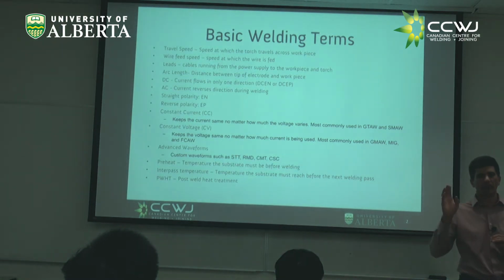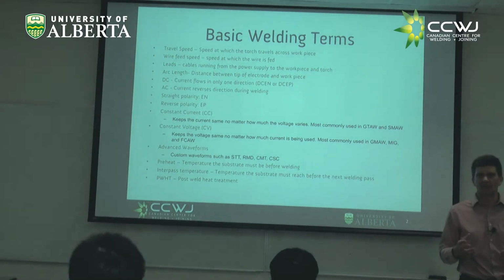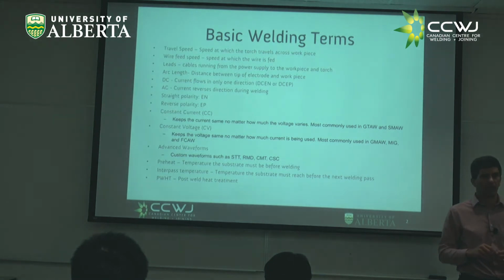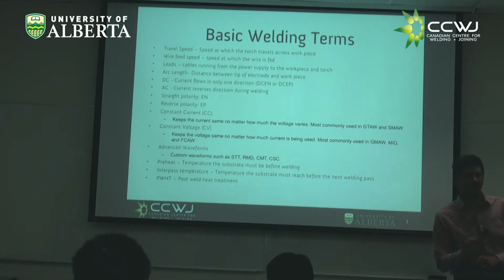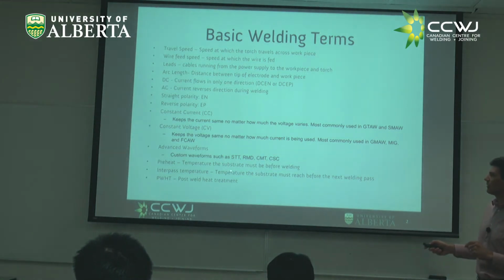If you have a weld that is too hard, then you can increase the preheat, and the weld is going to be softer. And this has nothing to do with the heat of the preheat softening the metal, right? This is amazing. And of course, everybody knows this. But not everybody knows why. Actually, many people don't know why. And people would start saying, oh, I'm a good welder, I don't need no preheat. And I say, no, you don't understand. It's about the laws of nature. It's not about your hand, right?